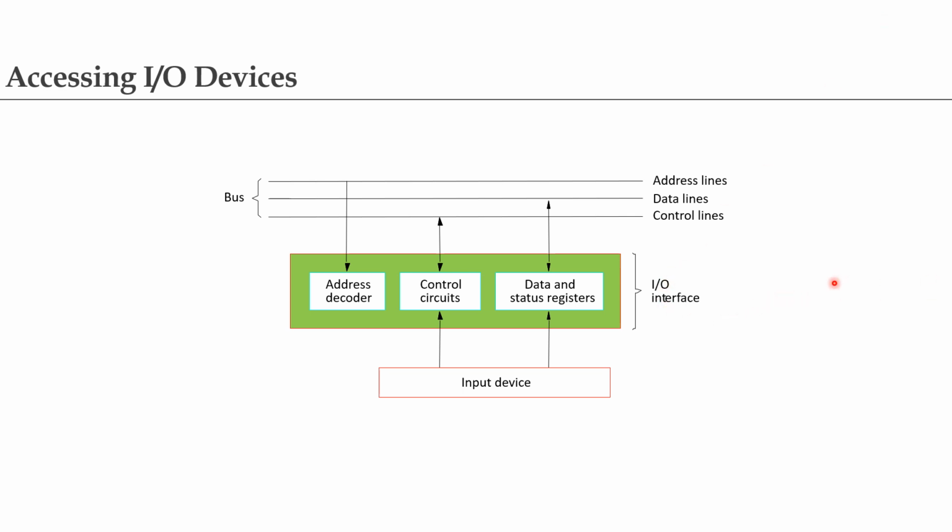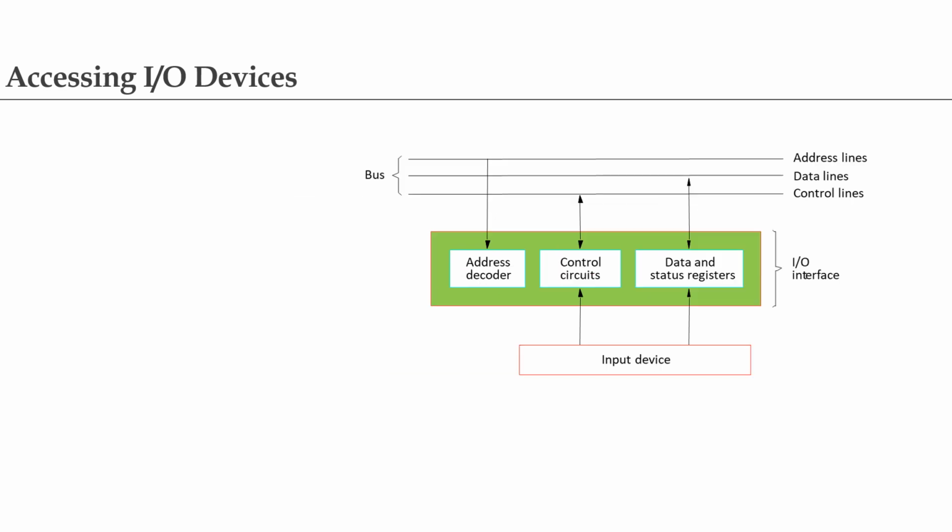When building a computer system based on the processor, the designer has the option of connecting input-output devices to use the special input-output address space or simply incorporating them as a part of the memory address space. One advantage of using a separate address space is that input-output devices deal with fewer address lines.